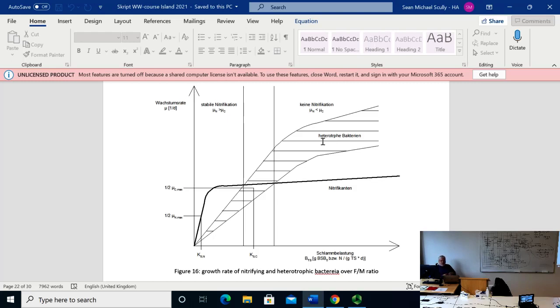No, because the number of microorganisms in the system is going to be constant. Because in your aerobic system, you have a certain volume of your tanks, and you will control your concentration of the MLSS. You cannot allow the MLSS to keep growing by not taking out surplus sludge, because if you do that, you have too high a sludge volume load on your final clarifier.